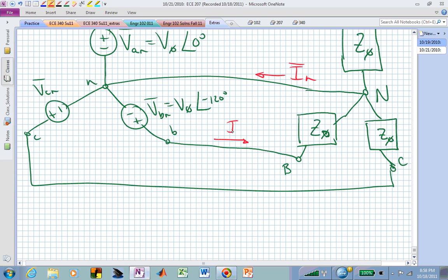We could say we have the B phase current going from the lowercase b terminal to the capital B terminal. That's then the direction of current flow by that arrow. Likewise, we can have the C phase current, which is I sub lowercase c capital C, moving from the source terminal lowercase c to the load capital C terminal, or the C phase of the load terminal.